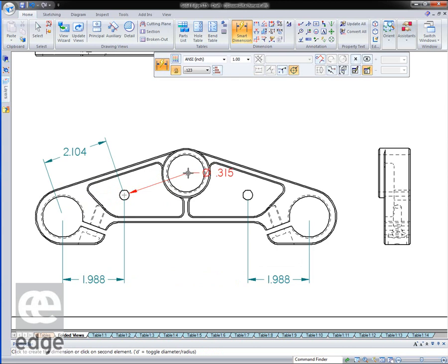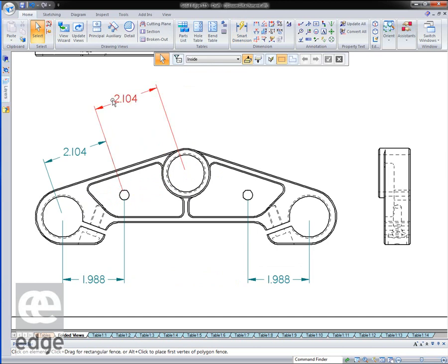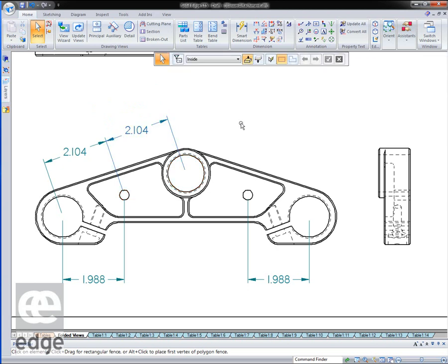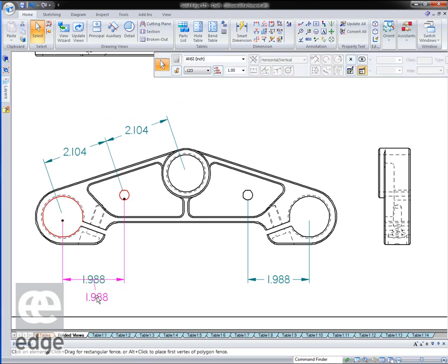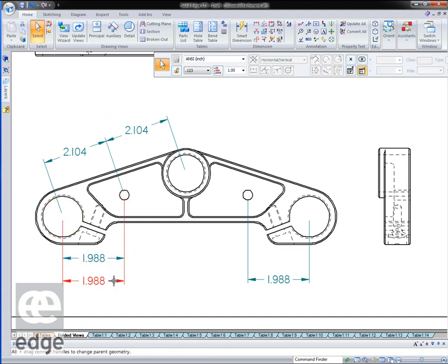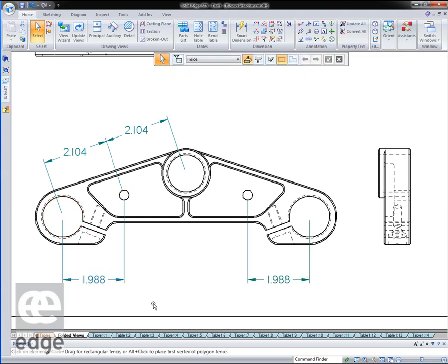Again, if we're doing one this way, I use the shift to put the angle in, and I'll put another one, but I'll put that somewhere else, and later on we come back and we want to align those. Again, I just move that dimension the normal way, click, touch on the previous one, and it'll align to it. So you can see that ability to align our dimensions after the fact is very powerful. Move that one out. I want to move it so that it lines up to here. Again, you see the alignment line, and it's lined up.